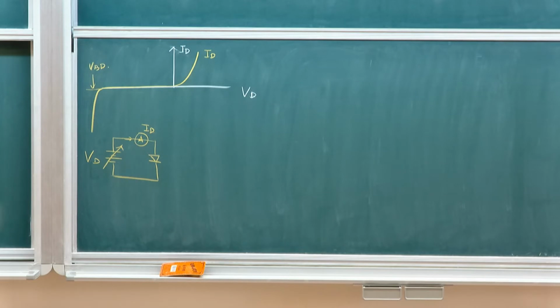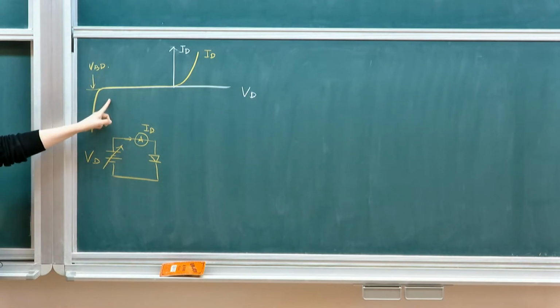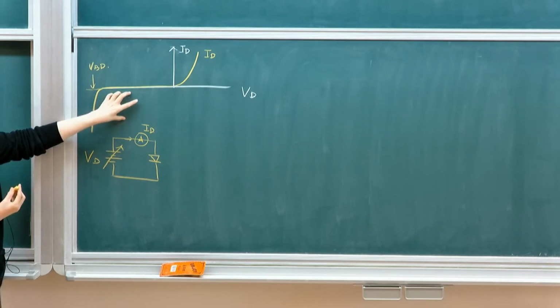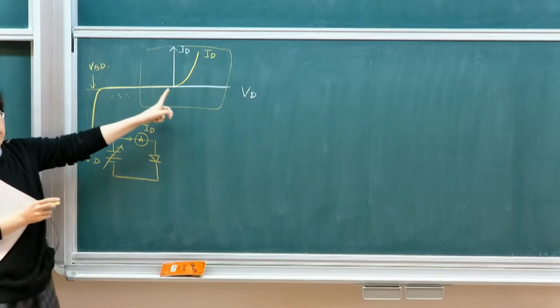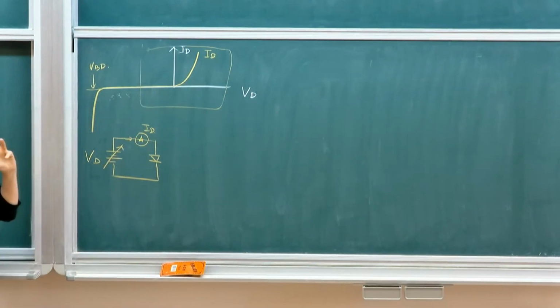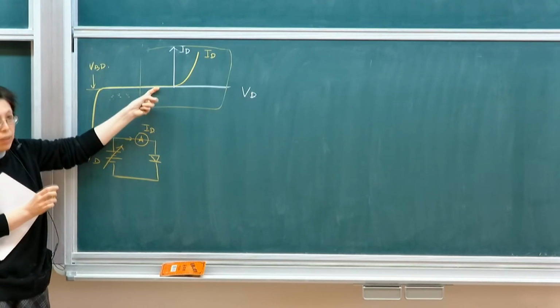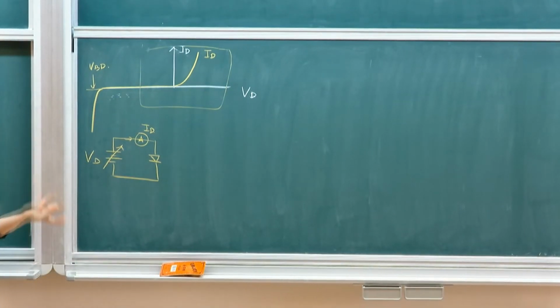if you're not sure whether your layout is wrong, or if you made a mistake, or if there's a problem with your own device process, one of the key parameters we ask every time I ask a student to debug is this typical characteristic. The first thing we want to see is whether you actually see this. This is very unique and typical for debugging. If you don't know what happened, maybe you misplaced your wire, the key thing is to see whether you see the diode characteristic in your circuit or in your device. Okay, so that's the key.